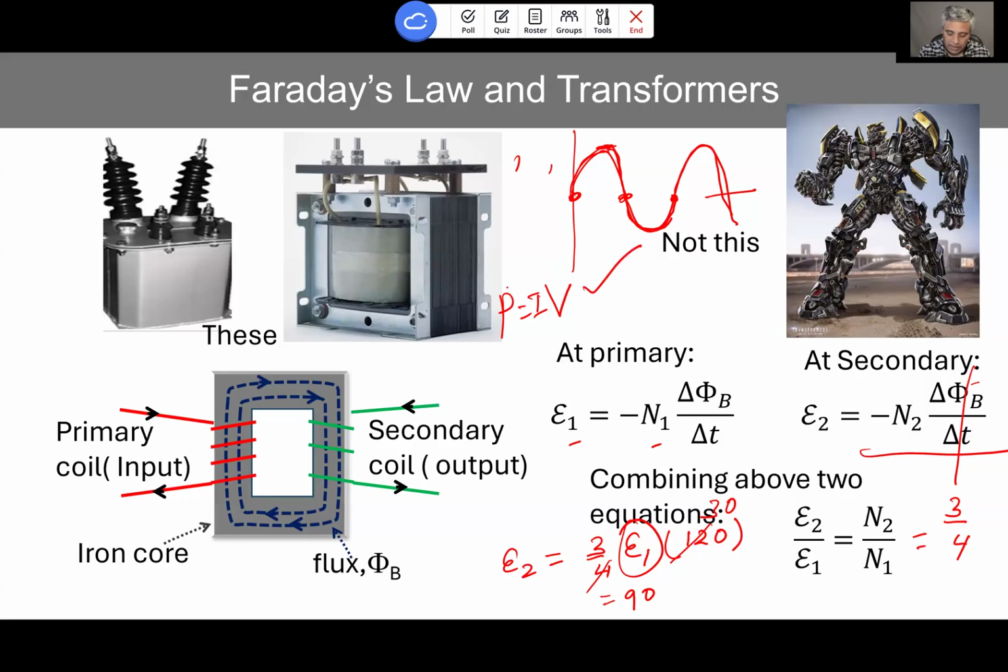So if you have low voltage and you are transferring large power, that means you have to transfer large current. And any wire has some resistance, and especially when you are transmitting kilometers or miles, the resistance becomes not so negligible. Because of that, the power you generated goes into heating this wire, and that is given by I squared times R. So this is the loss, because it just dissipates energy into the environment after the wire becomes warm. It's just dissipating energy, so it's losing power, right?